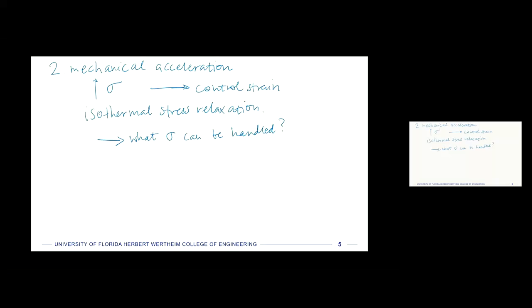Okay, and so this is plotted a little bit differently, but it's similar as far as taking data, extrapolating out, putting on constraints, looking at what you get. So I'll draw that on the next slide here. In this case, if it's a stress relaxation experiment, instead of creep strain on the y-axis, we're going to be plotting a stress level. And on the x-axis is still the duration in hours.